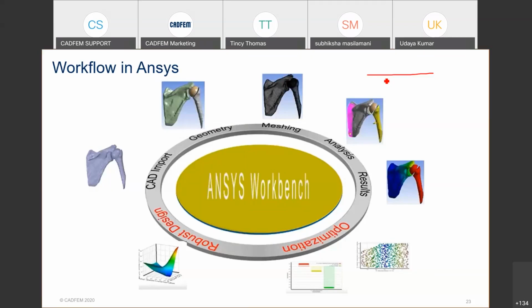the stick is here. If I'm fixing the stick here, and I'm applying a force and getting the data, I'm keeping a sensor here, and I'm keeping a sensor here also. This bends, and I have only two data points, right? One data here and second data here. So I can have only one data that is like this. But if I want to get all the data in between, you need different sensors here, right? At all these points, if you have different sensors, then you can get the actual deformation. This is how it deforms rather than a straight line.